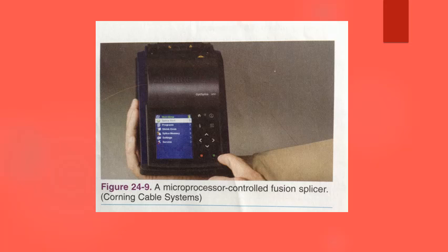A mismatch of sealing agent to core material can cause a grossly exaggerated signal loss. Care must also be taken to protect the cladding on the core when preparing cables for splicing. Damage to the cladding will result in signal loss.